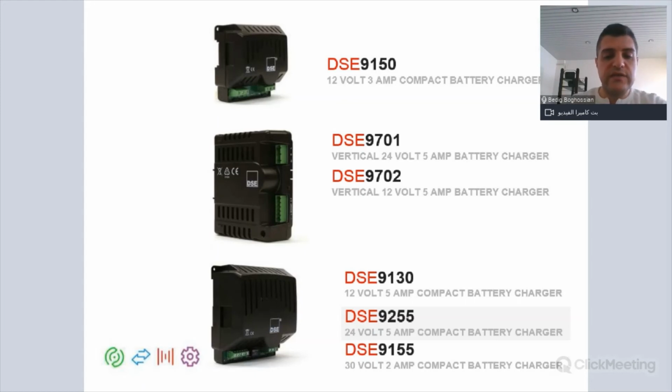Those are standard chargers. By the way, all DSE chargers can be fitted directly onto the generator without worrying about the cranking or protection of the batteries, because the DSE chargers have internal protections, which are short circuit protection and overcurrent protection.